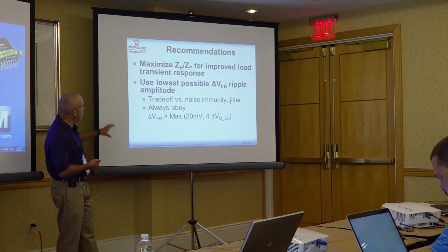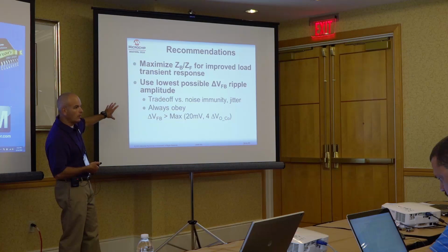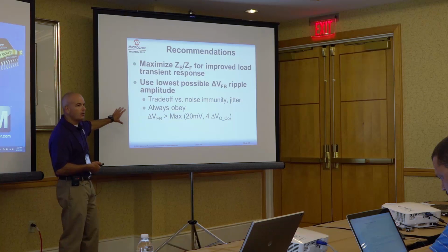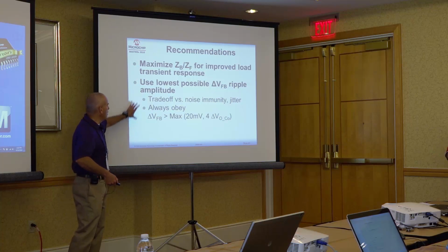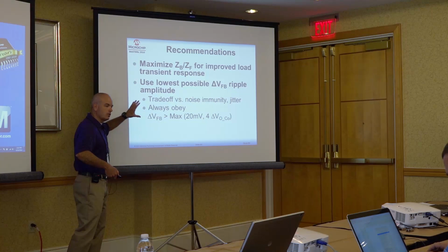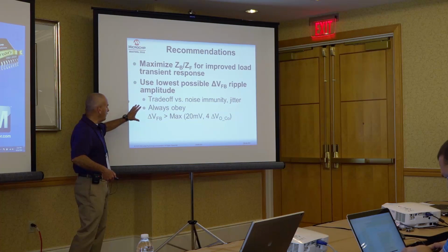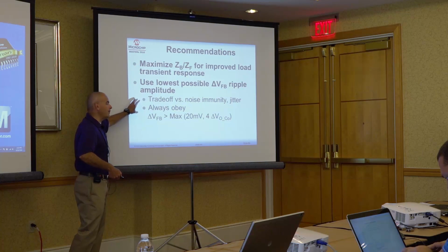Your best bet is to live with the lowest value of ripple injection, provided that you satisfy stability criteria and you are relatively free from jitter.